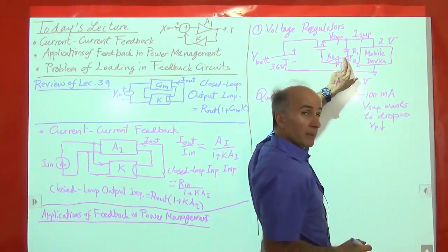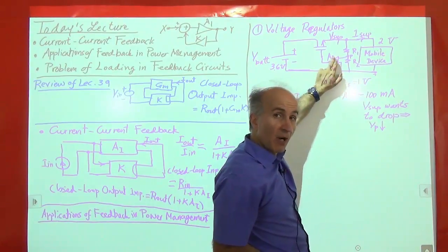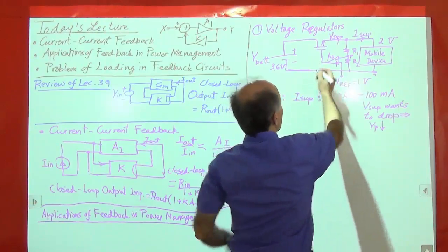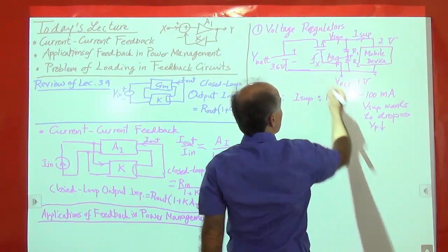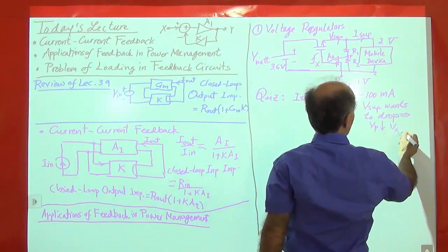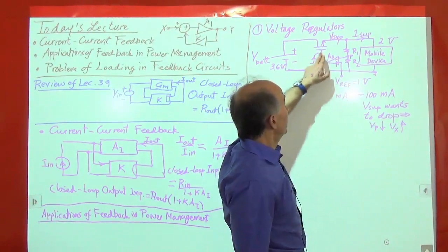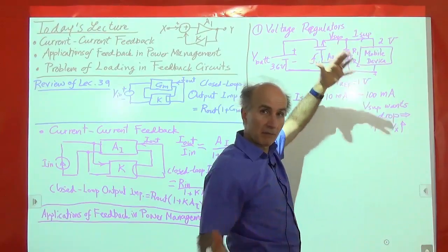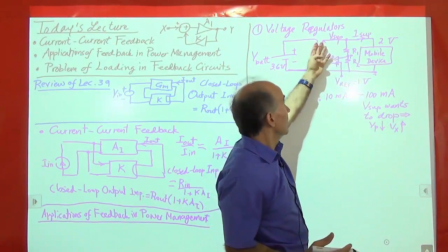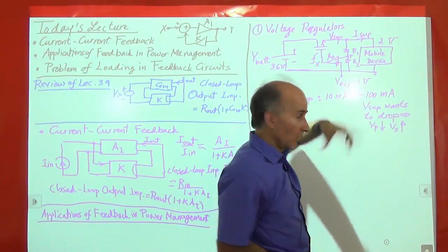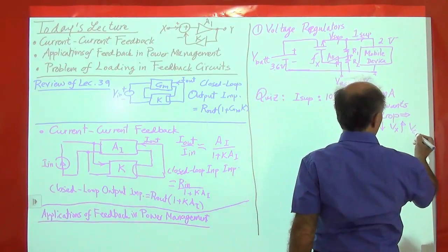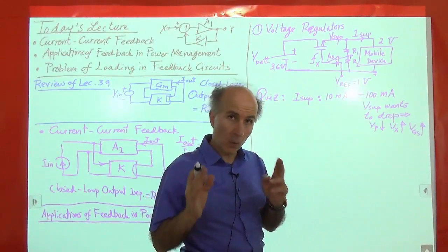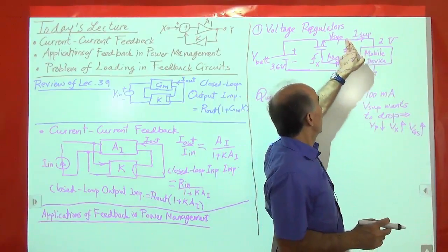This voltage drops. The op amp says, my inverting input has dropped. So what should happen? Its output should go up. So Vx, this one wants to go up. So Vx goes up and it turns on this MOSFET more, right? Because now you want to have a bigger VGS so that this transistor can still support 100 milliamps of current. So VGS of the MOSFET goes up. It goes up enough so that the MOSFET can deliver 100 milliamps while maintaining 2 volts at this point.